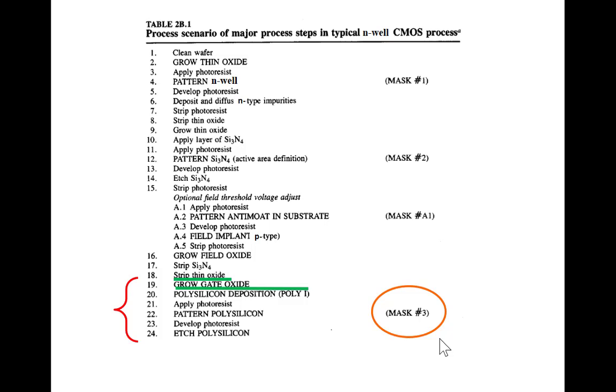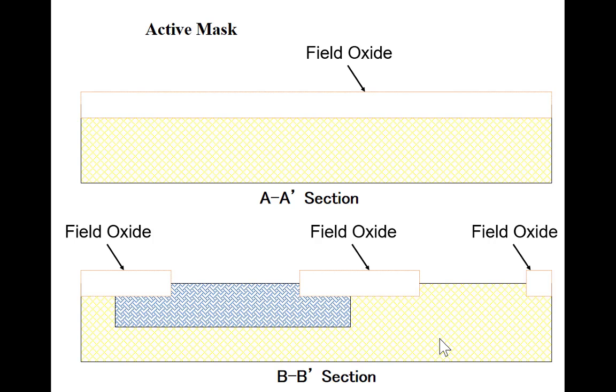Any questions so far? I should point out what this field oxide is doing. We're going to eventually run metal around to interconnect things together. Anytime you run a conductor on top of a doped region, you try to pull impurities to the surface. You try to create an inversion layer. If you have your metals close to the silicon, then when you put a voltage on the conductor, it will create an inversion layer and short everything out.